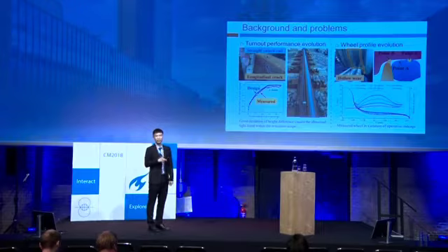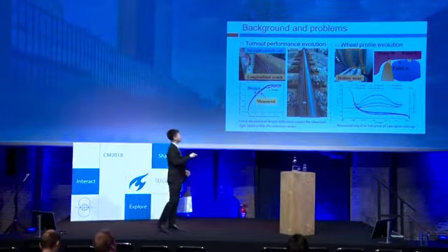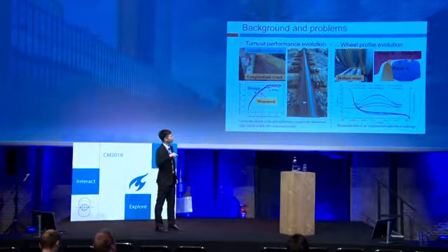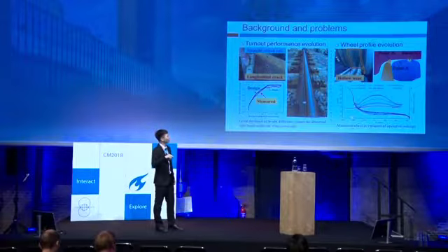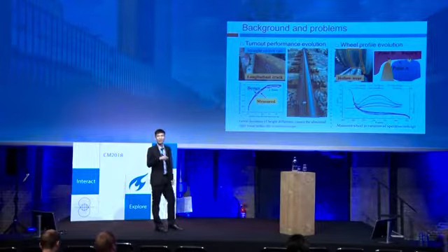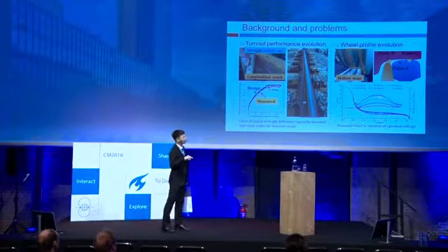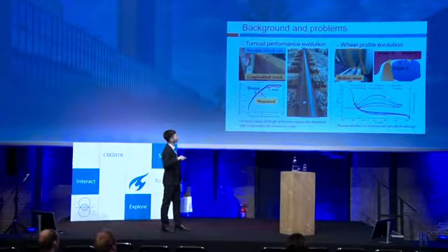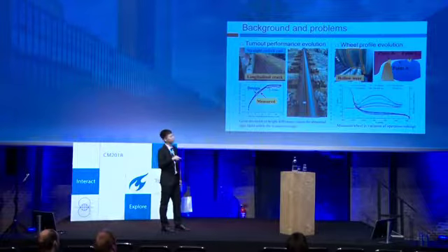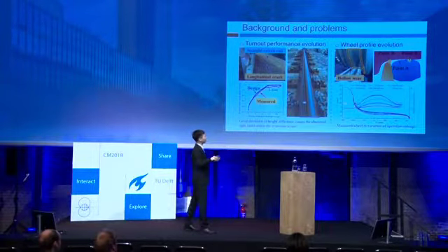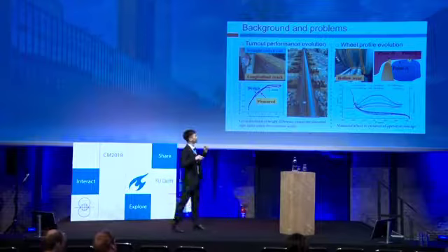Meanwhile, the wheel profile evolution will affect the wheel-rail relationship in the turnout. And the hollow wear is the most typical one. The figure in the lower right shows the measured wheel in a Chinese high-speed railway vehicle. And it is found that when the operation mileage reaches 250,000 kilometers, the hollow wear exceeds 3 millimeters.